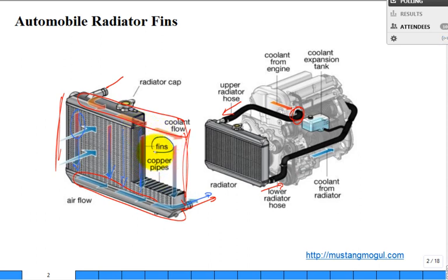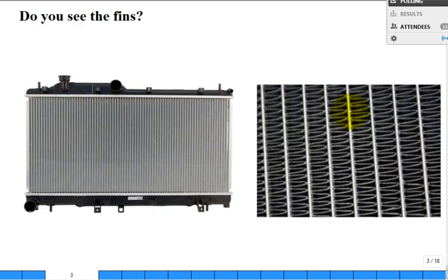what do they say right here? Fins. What are they finning? Not what the liquid water with the little glycol antifreeze sees. That's usually a pretty smooth little passageway through the radiator. It's what the air sees that's coming over on this side of that radiator. And so we zoom in a little bit, and when we zoom in we see, oh, this is my fluid liquid flow passage, and in between they put this material.